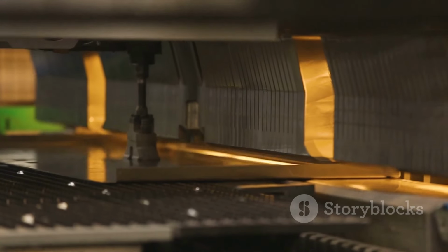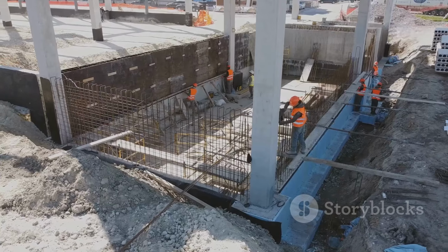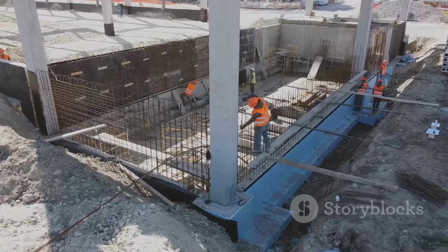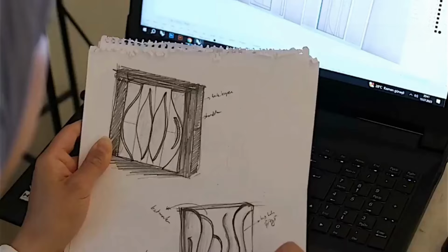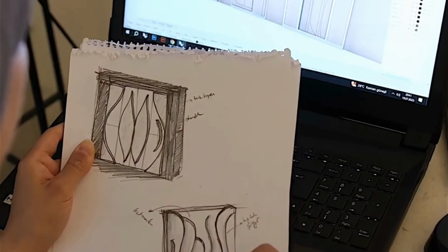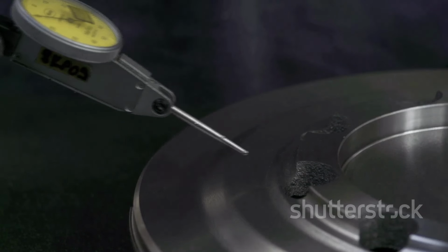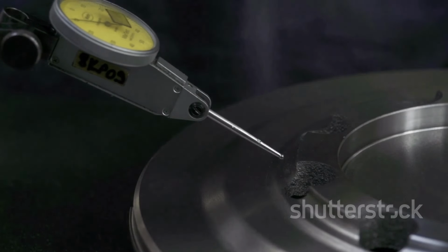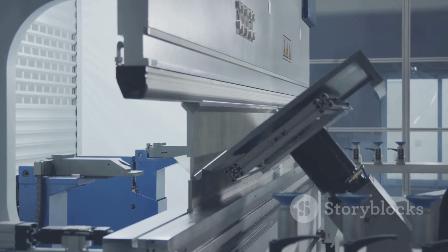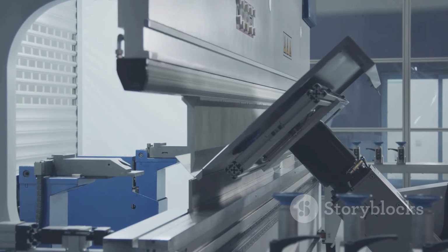Next, we need to define our base flange. This is the starting point of our sheet metal part, like the foundation of a house. We can sketch a simple rectangle or any other shape we need. SolidWorks will ask for the sheet metal thickness. With the base flange defined, we're ready to start adding bends and features.